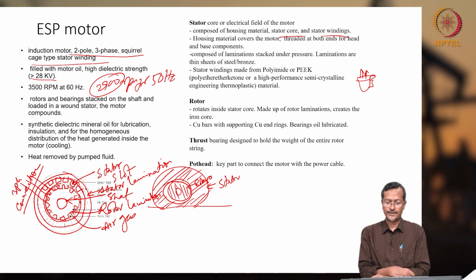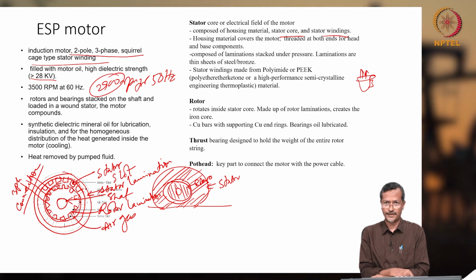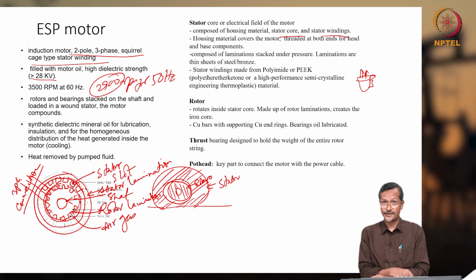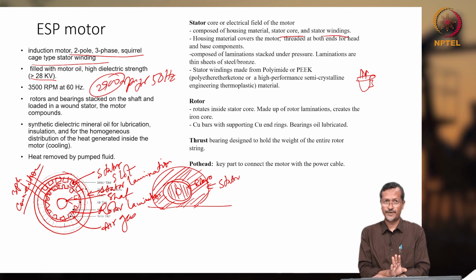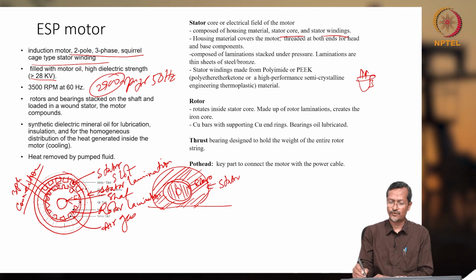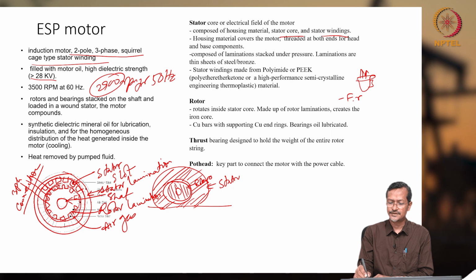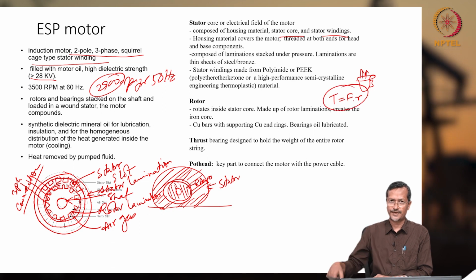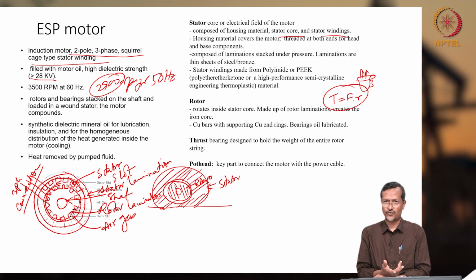A copper bus will be used in the rotor, okay, copper is a highly conductive material. So, you are not creating resistance there, rather you are creating force. Its main purpose is to produce force, right. Force will be converted into torque. So, how is force converted into torque? Force into radius equals torque. Okay. If the shaft radius is r and you are getting force F, then torque will be F into r.